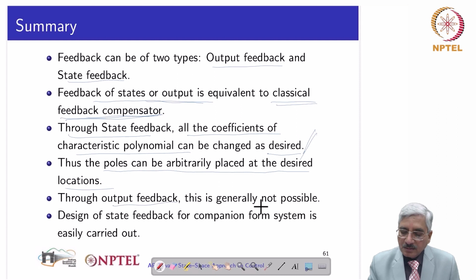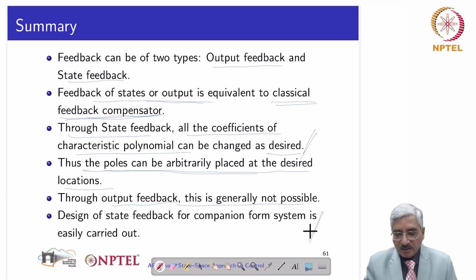With output feedback, this is generally not possible. Not all the poles can be arbitrarily placed. And we have also seen that design of state feedback for a companion form system is easily carried out.